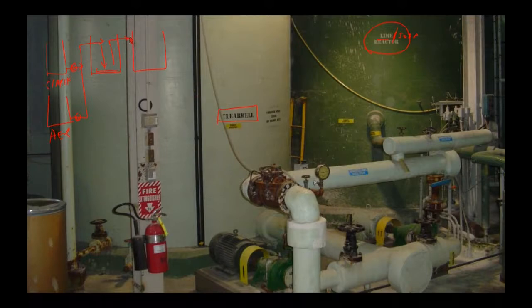Okay, so the clear water flows over into the clear well and sort of accumulates in there. So you have sort of like a water reservoir. Then what we're going to do is repressurize it. That's why we've got a pump here. There's another pump. Well, there's a standby pump somewhere. I can't see. Oh, here. Yeah, there. Okay, so we've got standby pumps and a regular pump, and that's going to put it now through the series of pressure filters that we looked at on Monday, and the carbon filter.